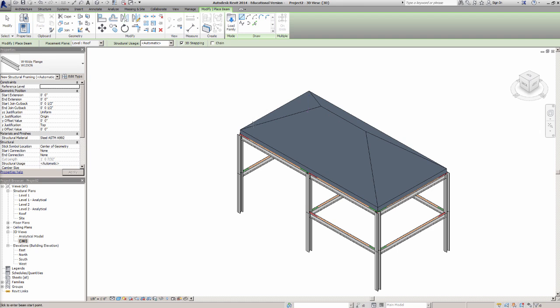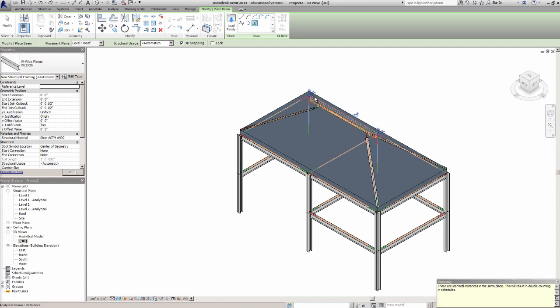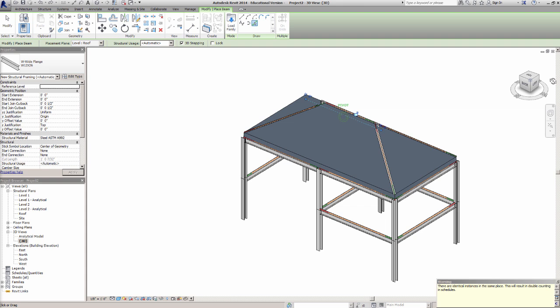Now you notice when 3D snapping's on, I can draw a beam, and that beam is going to come in whatever plane you have listed here. However, if I have 3D snapping on and I actually click on the pick a line element here, we can put beams directly in 3D. The previous beams, as they went in just in plan view in certain areas, and so this allows us to put beams along certain 3 dimensions between work planes.